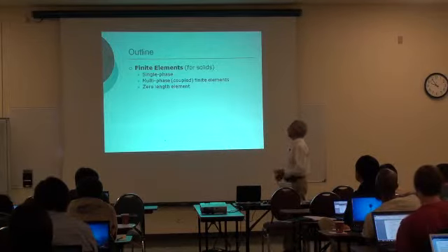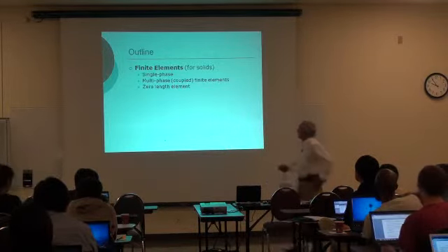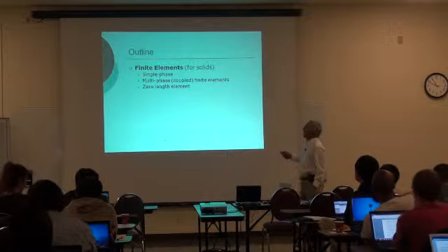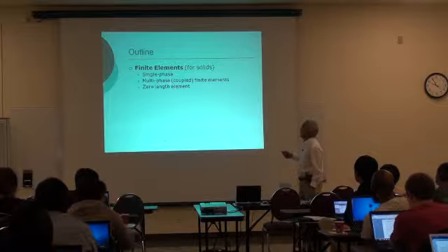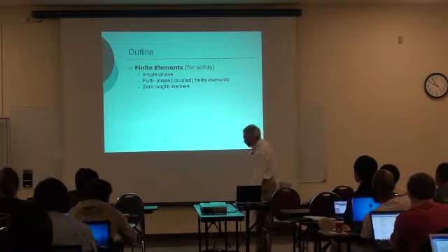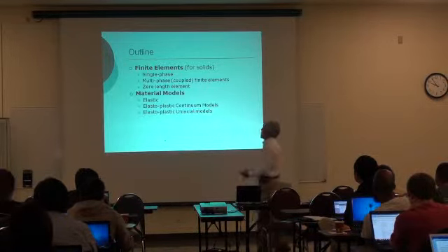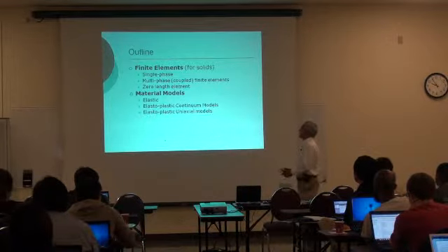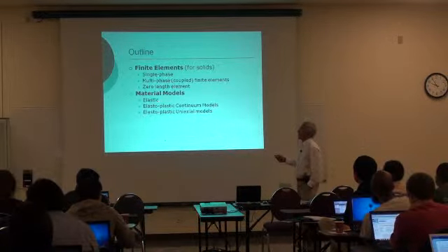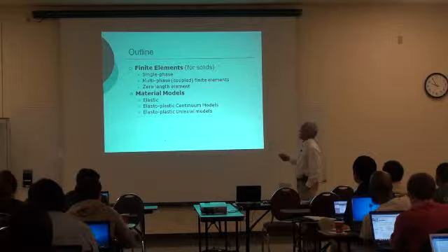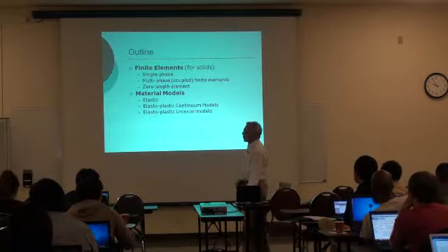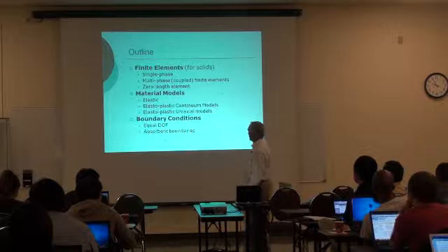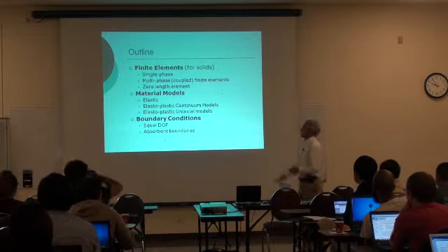So the finite elements for solids that are available, I separate into the single phase and the multi-phase elements and the zero length elements. When we look at material models, I look at the elastic models that are available, and also the elastoplastic continuum models, and also elastoplastic uniaxial models that could be used in order to characterize some of the response of the soil, or soil pile interaction, or soil structure interaction.